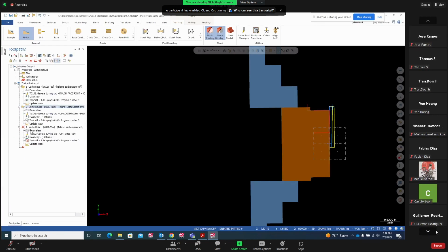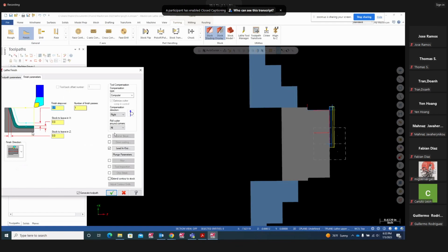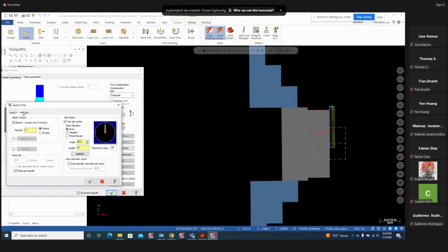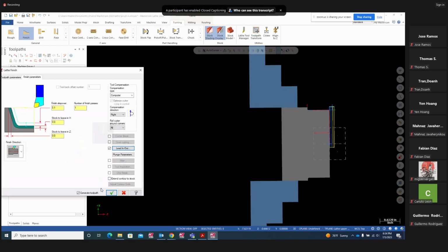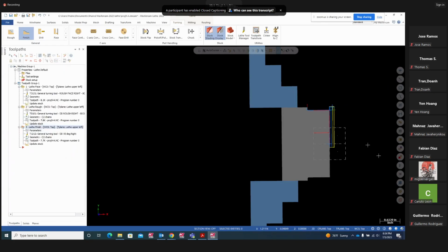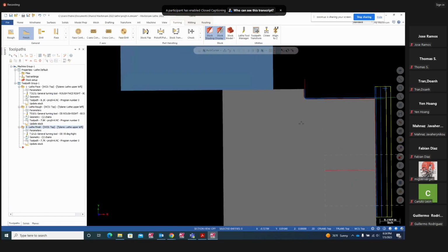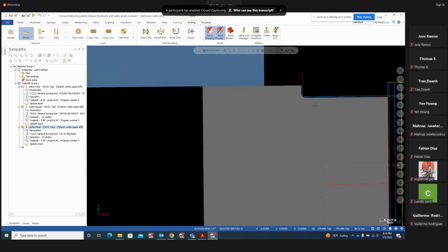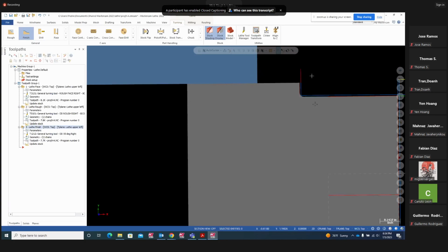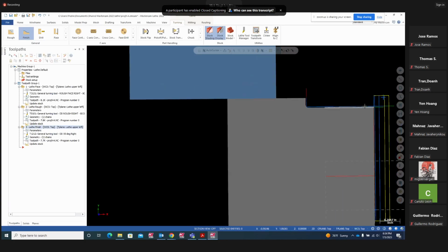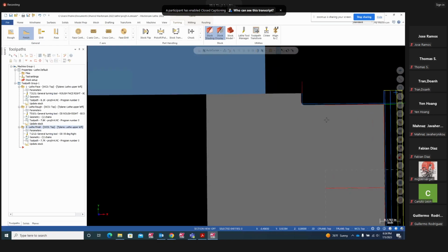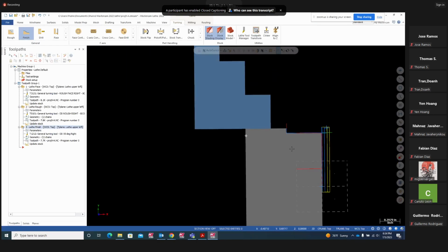And now I can go here with the finish too, same thing, lead out, go 200,000. And we are good. There we go. So here we have extra material where I can cut it off, that part right there. Our finished part is going to be up to here, 389. So we're going another 200,000 extra. That's good.